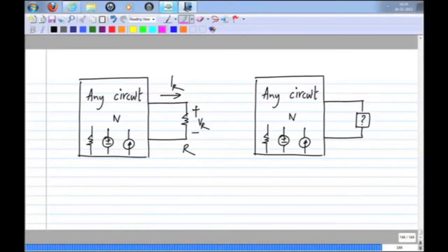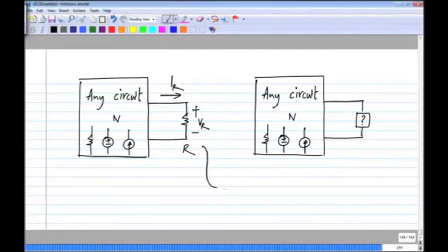Okay, I've got only one response, which says that this could be replaced by a voltage controlled current source. Now I'm not sure what is the intent of this answer. Perhaps it means that we have seen that a voltage controlled current source can behave as a resistor if the controlling voltage happens to be across the current source.